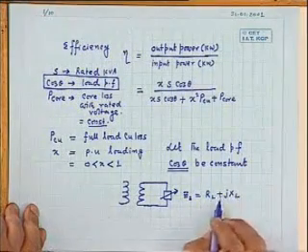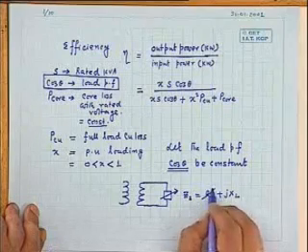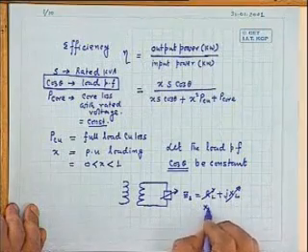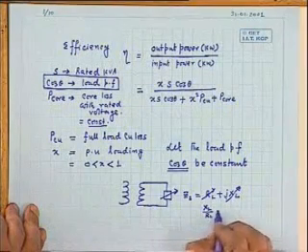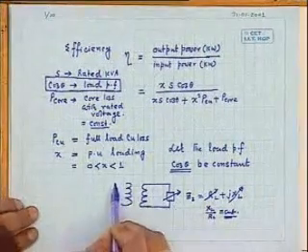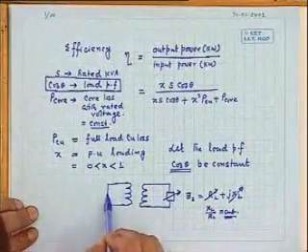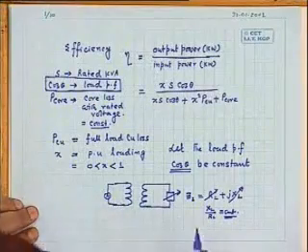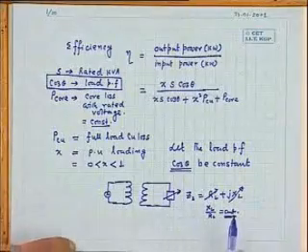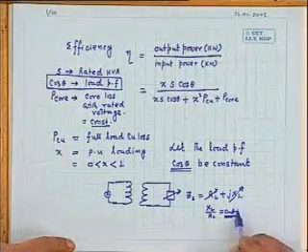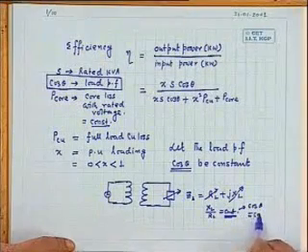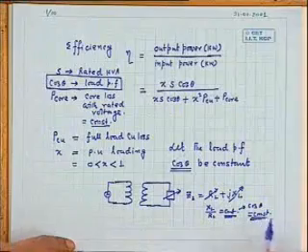This load impedance I am varying, but in such a way that both RL and XL I am varying, in such a way that XL by RL, this ratio remains constant, such that I will be able to draw different amount of current from the transformer, imposing different loading on the transformer, keeping the power factor constant. This will ensure cos theta constant. This way I will vary.